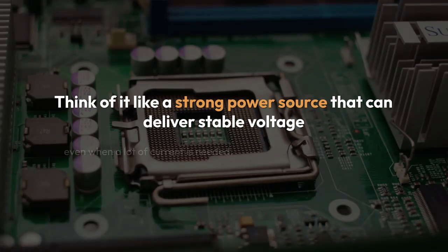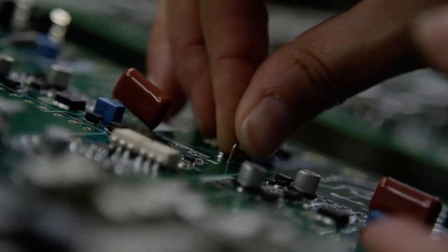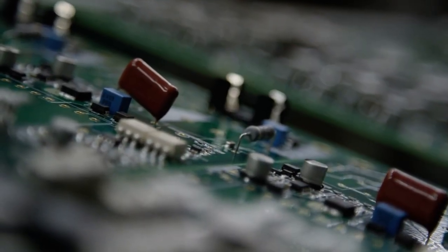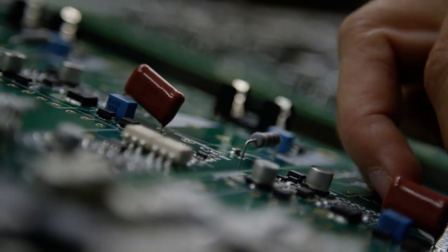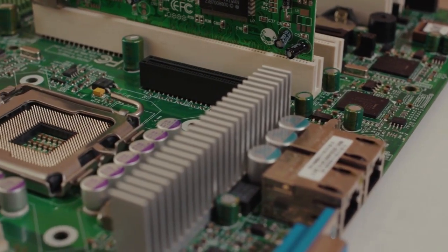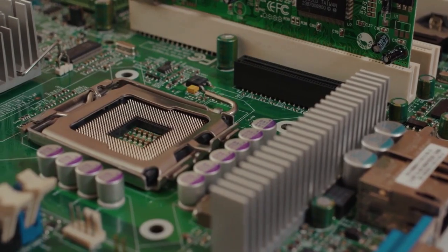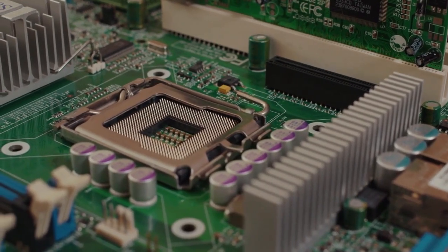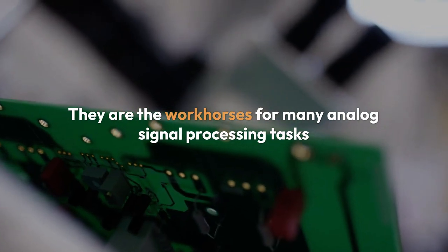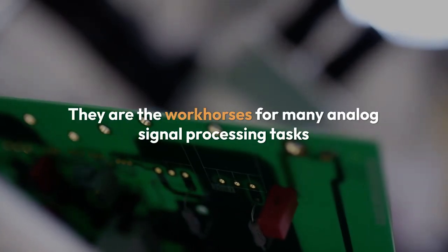Think of it like a strong power source that can deliver stable voltage even when a lot of current is needed. Op-amps are typically used with negative feedback, often with external resistors, to set a precise and stable voltage gain. This setup makes them perfect for applications like precision voltage amplification, active filters, summing amplifiers, and voltage buffers. They are the workhorses for many analog signal processing tasks where a stable, amplified voltage output is required.